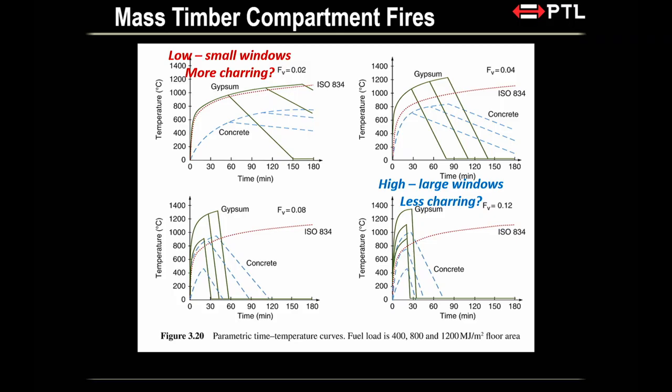And now you might wonder why. So I wanted to tell you the sort of idea about this. If you think about your oven, right? You have an oven that is going, right? But then you only open it a little bit, okay? So a lot of heat is still within your oven. Now, if your oven is made of timber, then the timber will char quite heavily in that particular scenario.